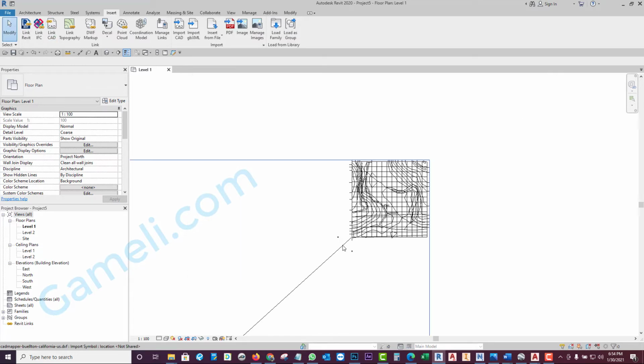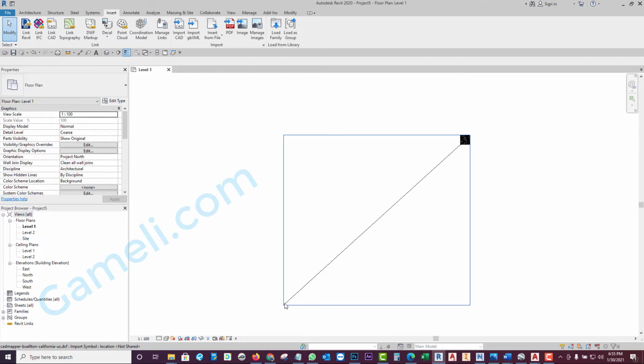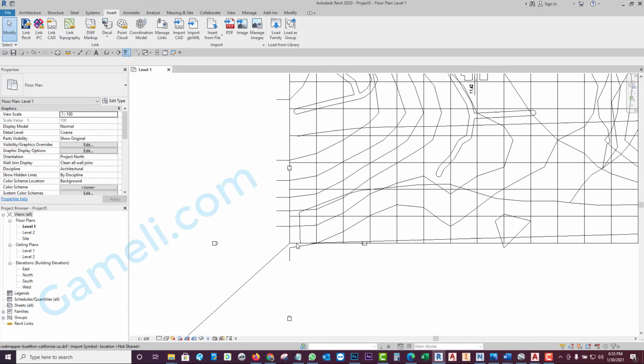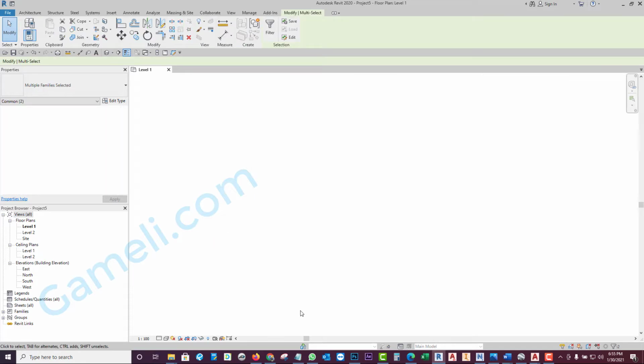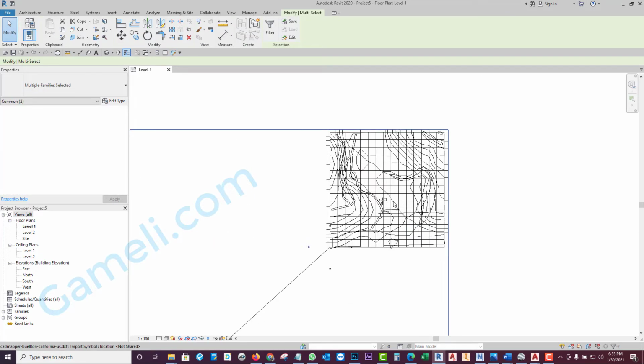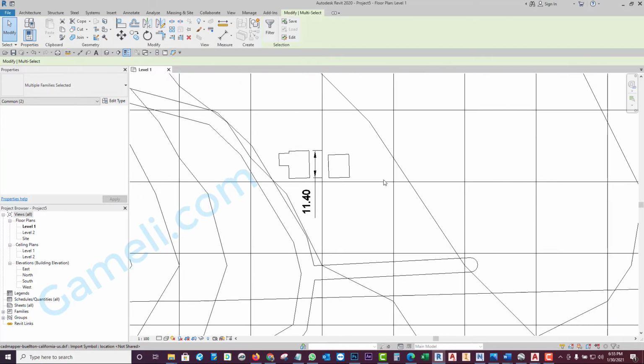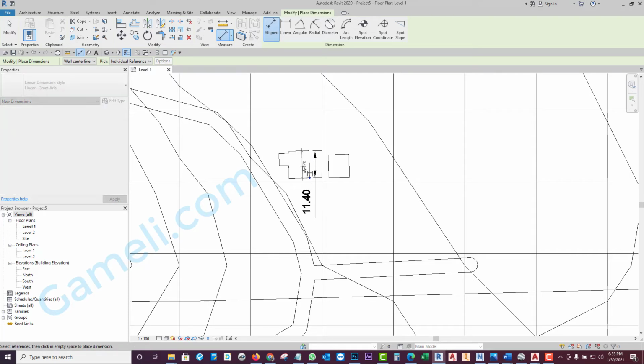I'm going to open. Because it has this drawing, it brings that line that I drew. Okay. But the origin is still here. Remember, in Revit, the center of these views, which is the elevation, is always the center, the origin. Alright, so origin to origin. We verify the dimension now. Let's draw a dimension from here to here.